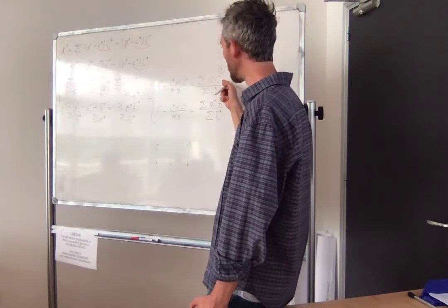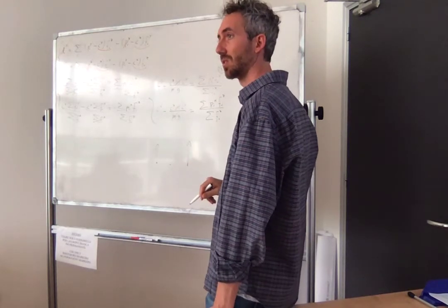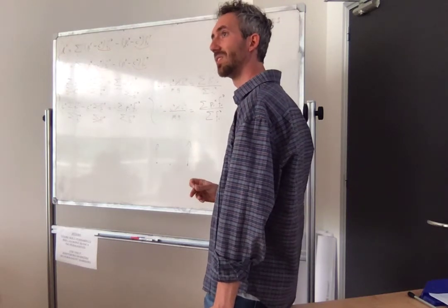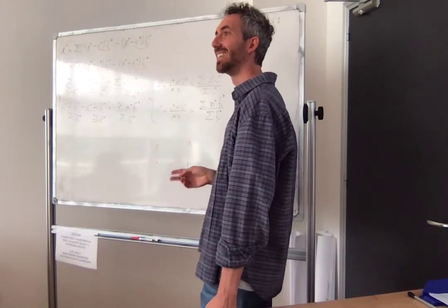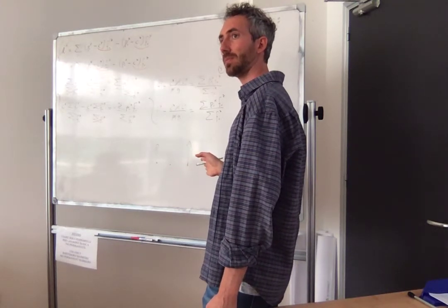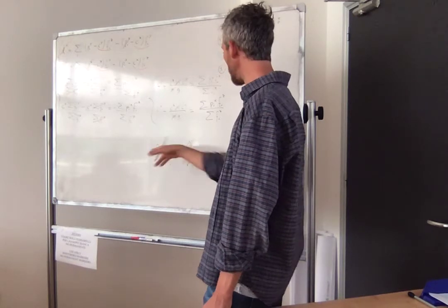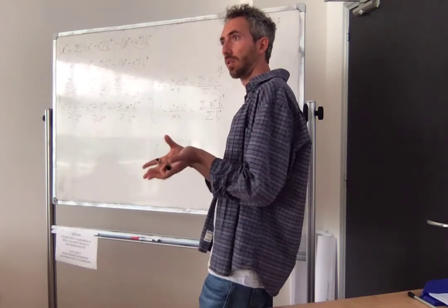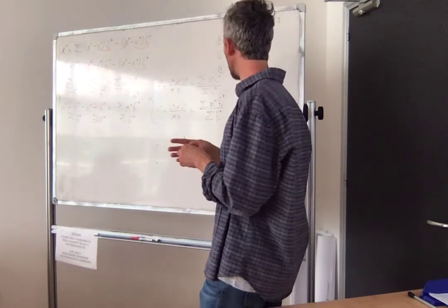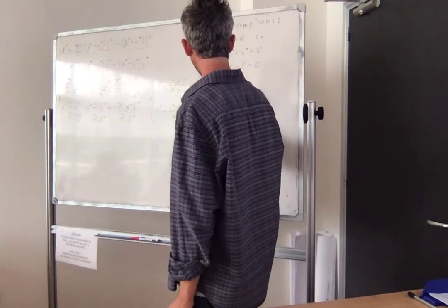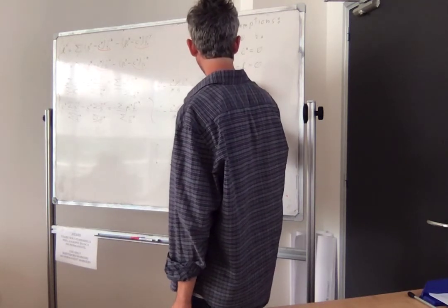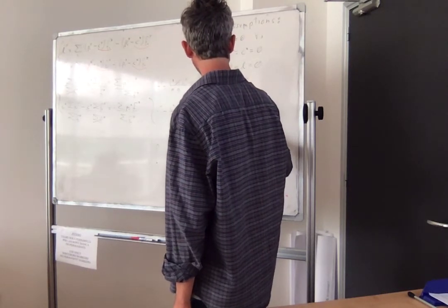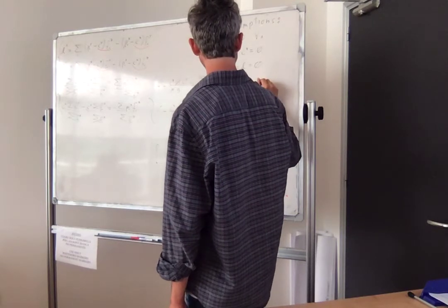So what is the physical meaning of this? Yeah, Gastone said it. Or Marco said it. Center of pressure. It's the center of pressure. Okay, that's a weighted average of the contact point weighted by the normal forces. That's exactly the definition of the center of pressure. Okay, so we can say that our new control variable is going to be called Z, which is the center of pressure.